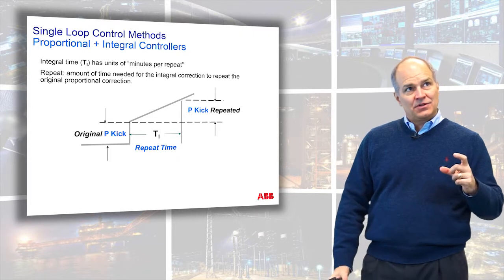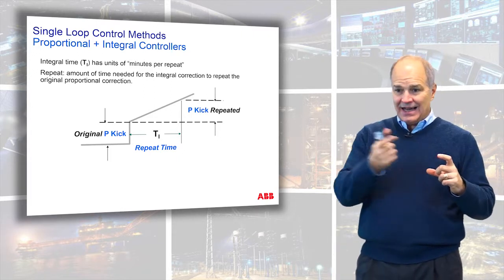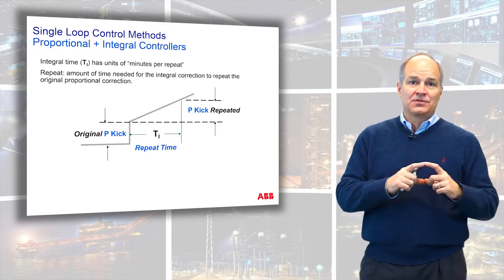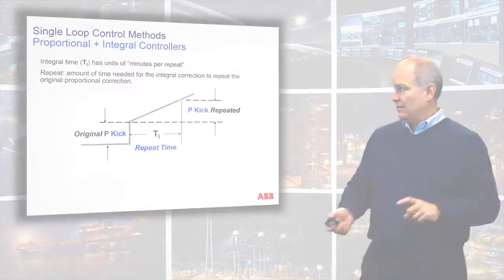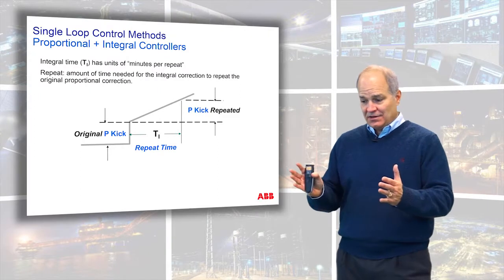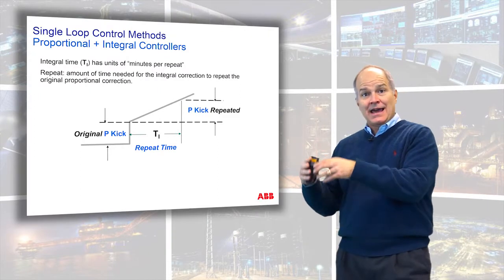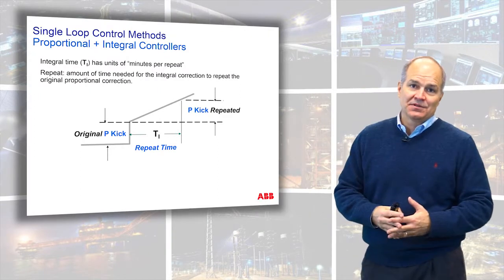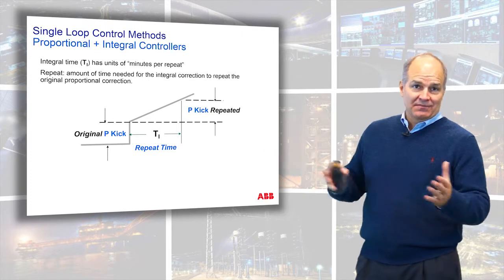And someone said, it sure would be nice if the integral time was related to that original proportional kick. So they said, okay, here's my original proportional kick. How much time does it take for the integral to add up to the original proportional kick? That's called the repeat time or the reset time. You're not resetting anything. It's just a measure of time until the integral has added up to the original proportional kick.